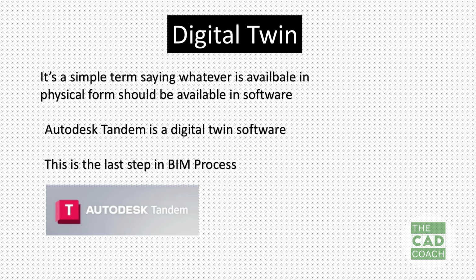So let us iterate the process that I explained. We create a 3D building model with the BIM authoring tool and CDE combined. We create a beautiful 3D model, the model is data rich, and we extract data through different software, do analysis and give the data back to the 3D model, and finally we create drawings and save them in the CDE. Then the drawings are used on the site for construction. Once the construction is done, we give all the construction details to the 3D model, and the 3D model is given to the client. This is the whole BIM process in a simple, concise manner.